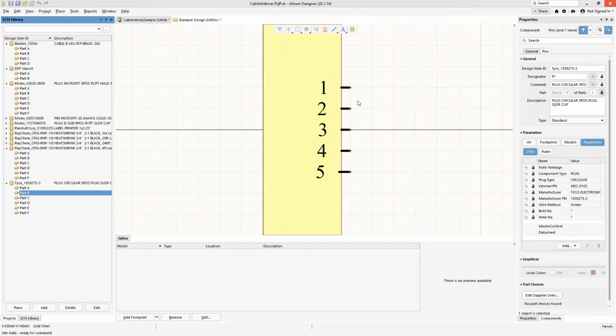Well, there's actually two reasons. One, we kind of abandoned midstream, and the other one was really more practical, which I think still makes sense. Originally, the idea was that we wanted these pins to be on the 50 mil grid so that if a pin had to be inserted in there, it would correspond to the 50 mil grid. And then by the time it was done, everything would be on the 100 mil grid. Of course, not everything requires that because, for example, the sub D9 with the solder cups in it doesn't require it. However, the other thing that we thought about is that we don't want anybody to confuse this cable piece with something that is being used for a printed circuit board.